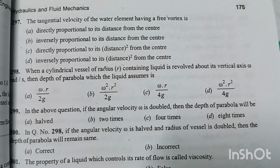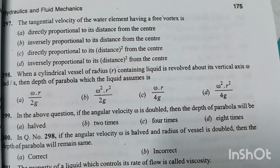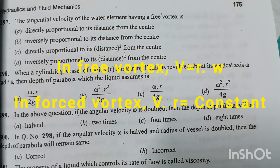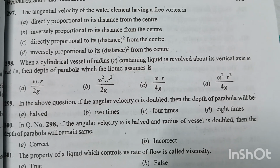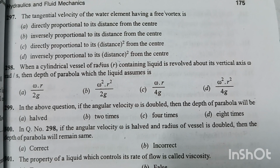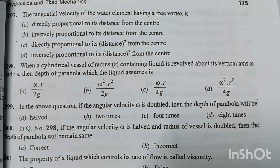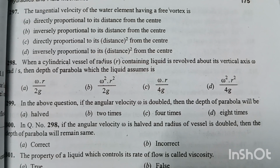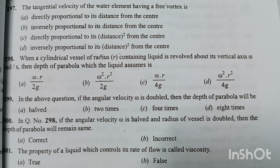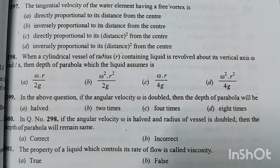Question number 297. The tangential velocity of water element having a free vortex is inversely proportional to its radial distance from the center. Option B is right answer. Question number 298. When a cylindrical vessel of radius r containing liquid is revolved about its vertical axis at omega radian per second, the depth of parabola which the liquid assumes is omega square r square divided by 2g. Option B is right answer. Question number 299. In the above question, if the angular velocity omega is doubled, then the depth of parabola will be 4 times. Option C is right answer.